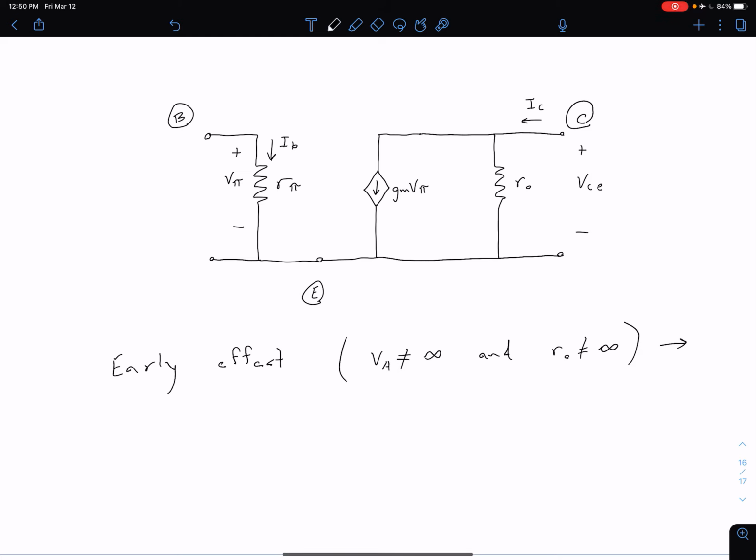What this does is change our voltage gain equation. And that's just if we're looking at voltage gain. Of course, we could be talking about current gain or various other types of amplifier, which we're going to look at later. But suffice it to say, adding a resistor in there is going to change our relationships a little bit, and most of the time it has the effect of reducing the gain.